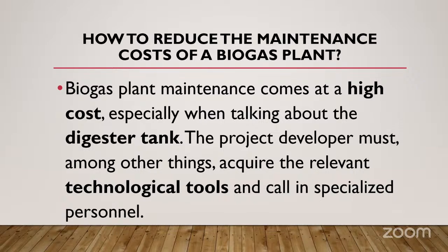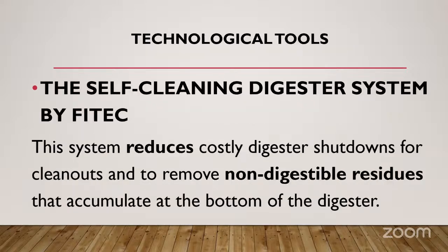It's a self-cleaning process, but sometimes you have to remove non-digestible residues. When you are feeding your digester, you feed it with different materials, and some materials can be non-digestible. When there is a big amount of them inside, the efficiency is going to be low, and you need to remove these non-digestible materials.